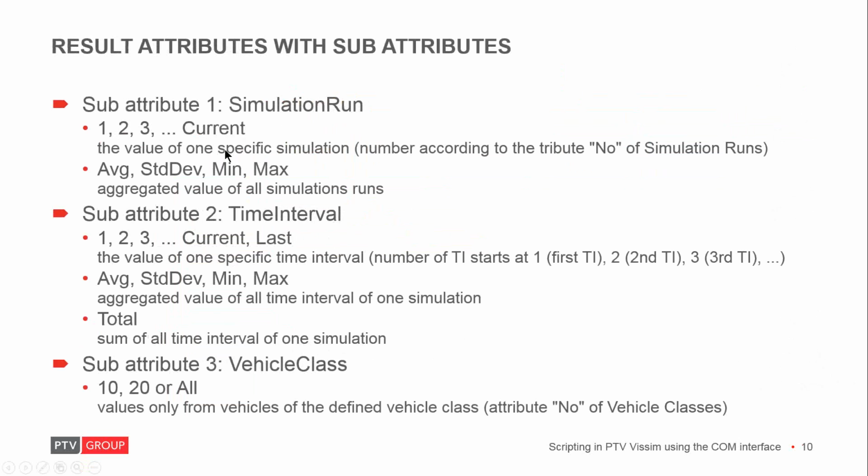What you also can do, you can also get the current simulation run. You can get aggregated values. If you enter, for example, instead of the number of the simulation run, average or standard deviation, min or max. You can also do that very similar in the time interval.